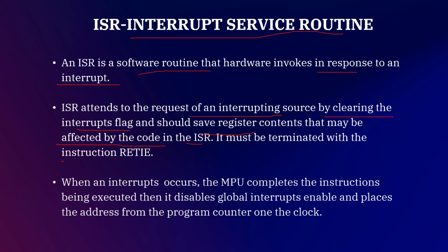When an interrupt occurs, the MCU completes the instruction being executed. Then it disables global interrupts, and places the address from the program counter on the stack.